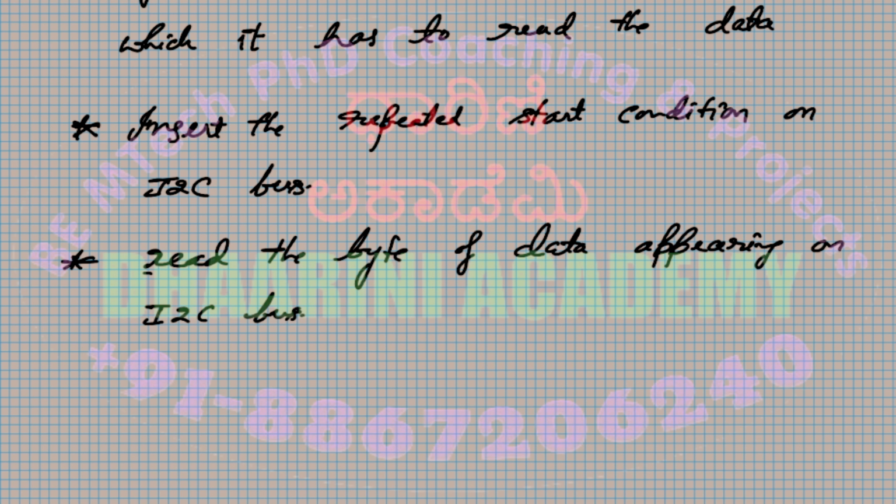Okay, so then you can simply stop it, right? The communication is over. Stop condition. Okay, right. So this is the procedure to be followed to read a data, by specifying the address on the EEPROM and reading the data that comes from the EEPROM on the data line.